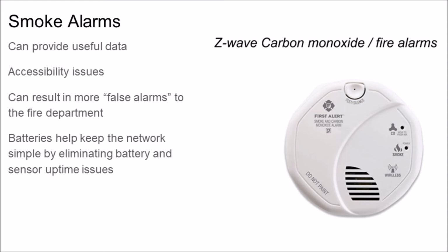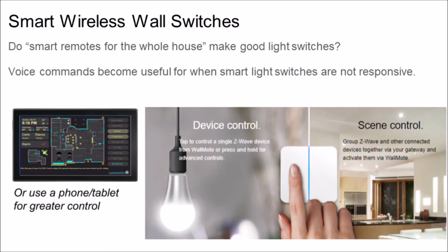So pairing the smoke detectors to a security hub can result in more false alarms being phoned in to the emergency responders, but failing to pair the smoke alarms into the security hub means that they will only function as local alerts rather than have a more automated security function. Now, regardless, I recommend hardwiring these smart smoke detectors rather than leave them to battery power.